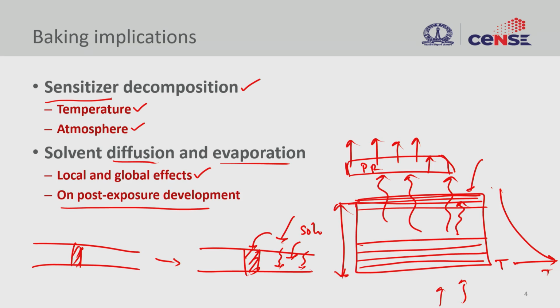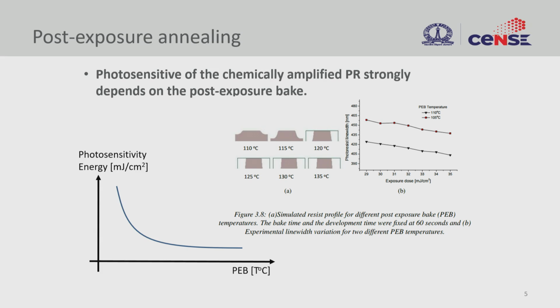The way to understand is by looking at the photoresist sensitivity to the particular solvent, right? Whether the solvent will diffuse into this photoresist or not. So in order to understand that, read the photoresist data sheet, right? There is no generic rule that a particular solvent will dissolve or not. So they always go in pairs, right? So make sure that we understand this diffusion so that we can avoid this undesirable diffusion into the material.